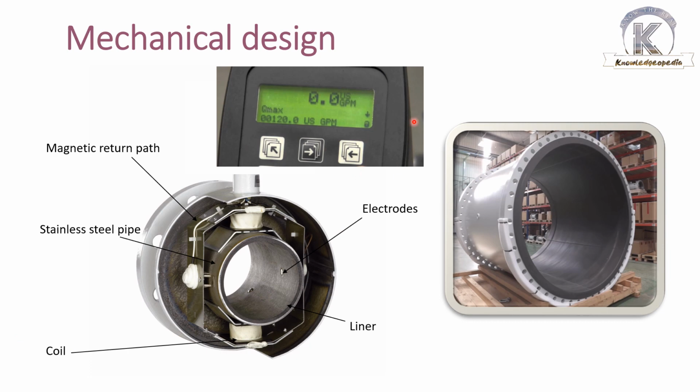Okay, so one of the advantages of the electromagnetic flow meter is the design without obstruction. You can see there is no obstruction. It's the finished product. You can see there is no obstruction to the flowing process fluid. That means the meter provides measurement without any additional pressure loss. And the full bore without any moving parts means that the meter can also be very easily cleaned. The cleaning is very easy. This partially explains the attractiveness of the meter to the food industry.